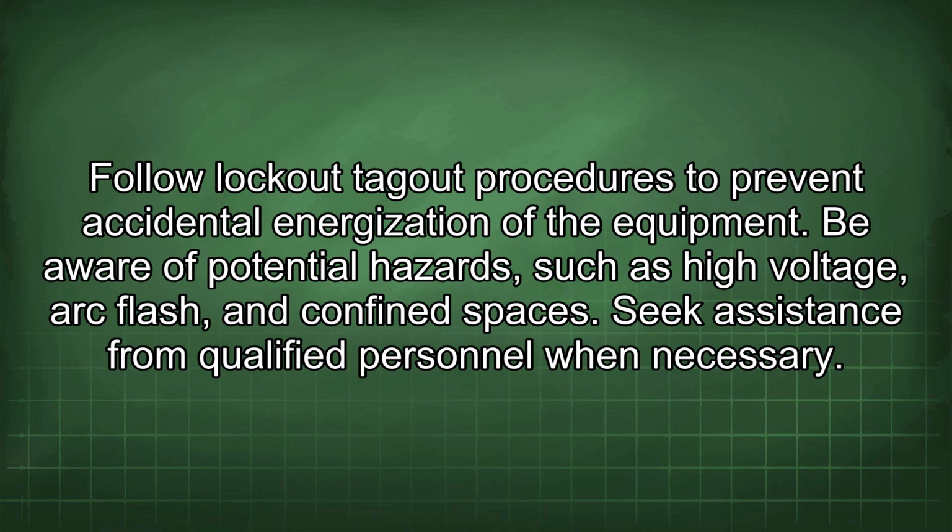Follow lockout tagout procedures to prevent accidental energization of the equipment. Be aware of potential hazards such as high voltage, arc flash, and confined spaces. Seek assistance from qualified personnel when necessary.